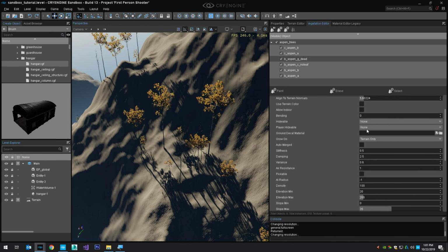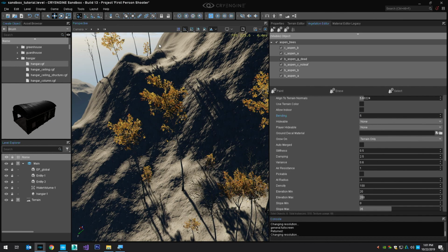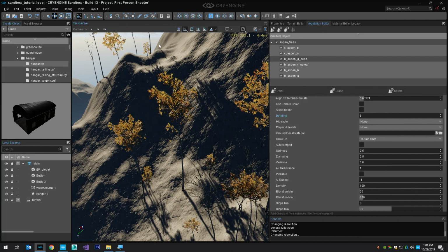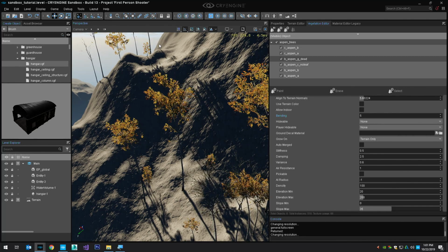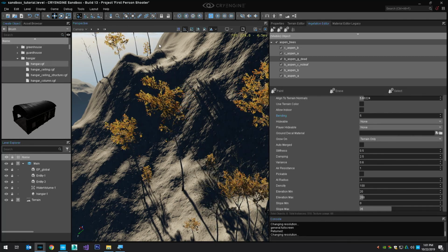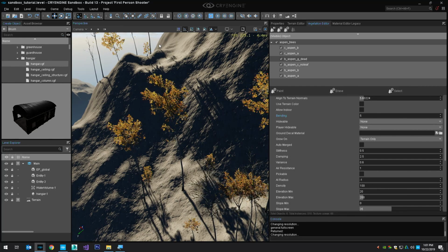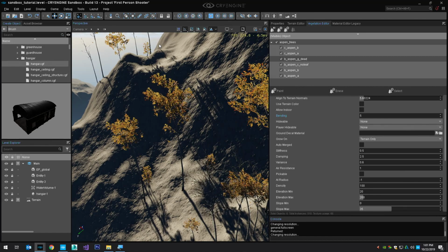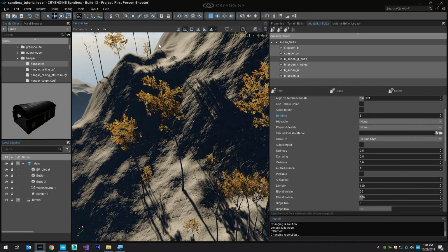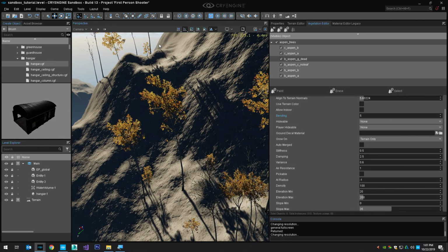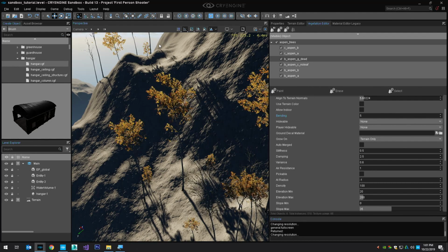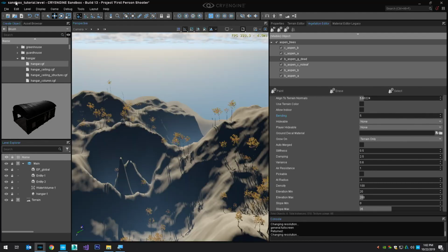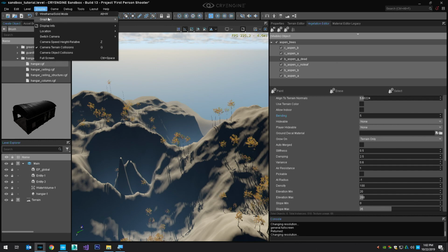Depends on how strong the wind is. I'll try maybe 5. And that looks pretty good to me. If you set it to a high number, you'll see ridiculous, rubbery trees that don't look very real. And again, this is directly affected by the real wind velocity. If you make the wind very strong, you may want to change this again. Like I said, something that shouldn't move, like a rock or a bush, something very stiff, like a dead tree, you should not use bending.